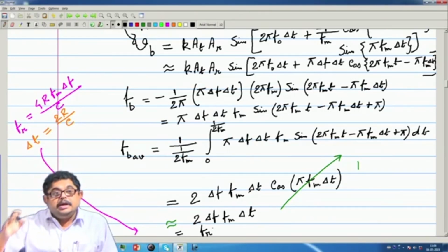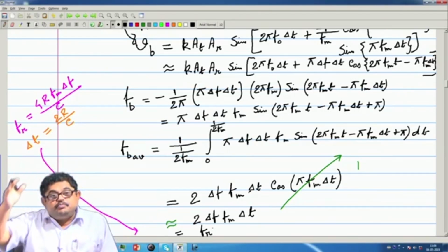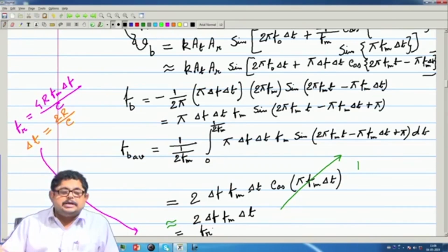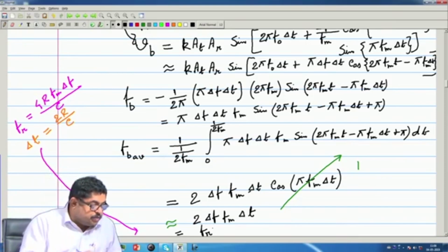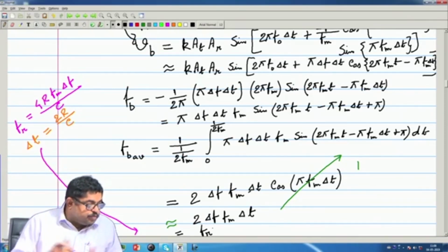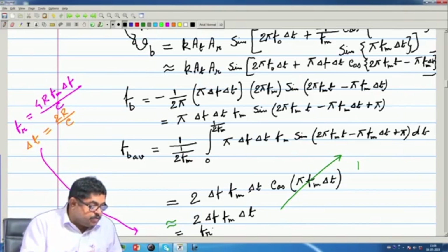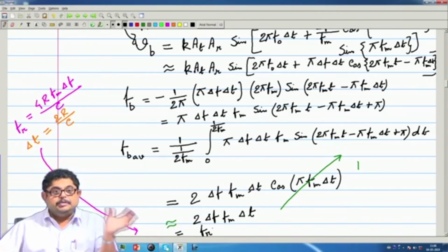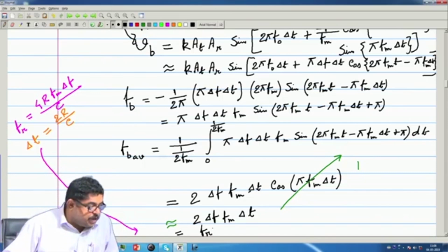The only thing you need is a positive cycle and a symmetric negative cycle. So, various other types of modulators are also used. Also Doppler shift, if it is present, it will be there. So, upsweep and downsweep time should be equal, that means the symmetry should be there.